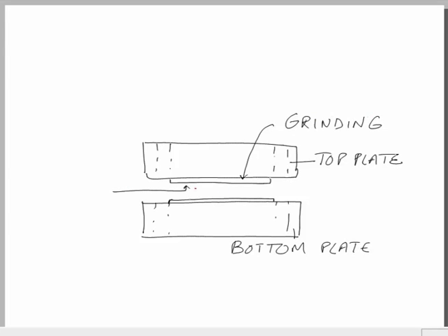So, the surface finish of these two surfaces should be very high. Why does the surface finish have to be high? Because this surface finish would be duplicated onto the composite product that we are going to make, and on these two plates the layup would be done.